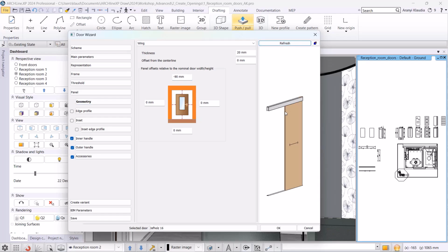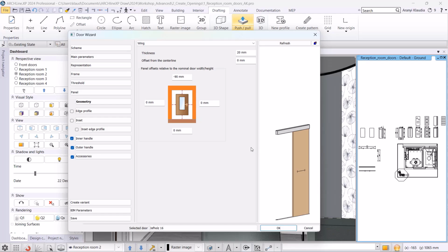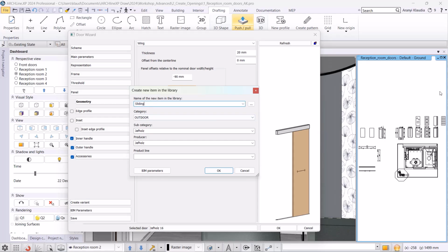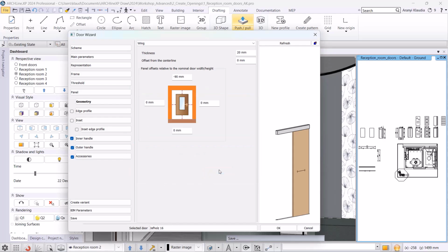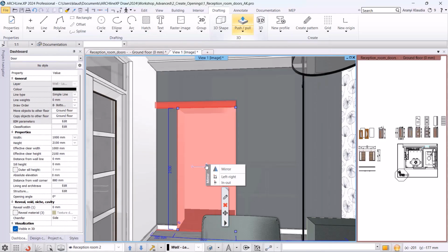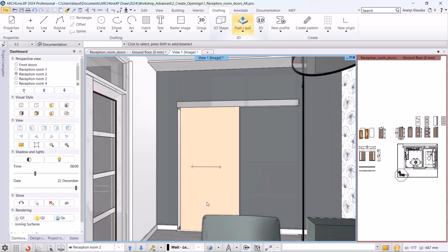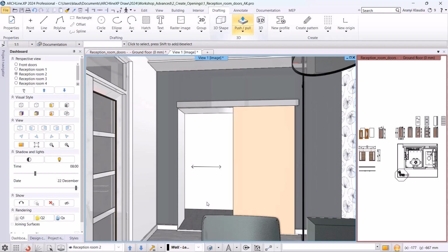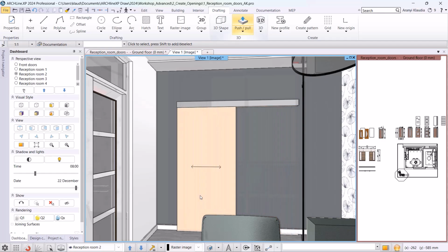What I still have to adjust is that I have to move the upper side to minus 90 mm so the wing will fit nicely into place. And in fact, we can place inserts in it, in the same way as we did for other doors during the workshop. And I will also reverse the opening direction so that it opens to the other side. Finally, let's do a 3D opening animation to see how this sliding door opens.